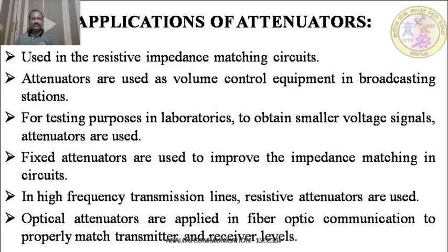Fixed attenuators are used to improve the impedance matching in circuits. Already I explained, impedance matching is to match the source with the load. You are going to use attenuators in such applications. In high frequency transmission lines, resistive attenuators are used, and optical attenuators are applied in fiber optic communication for proper matching of transmitter and receiver levels. In optical communication also, nowadays you are using attenuators. Like this you can use attenuators in many communication related applications.